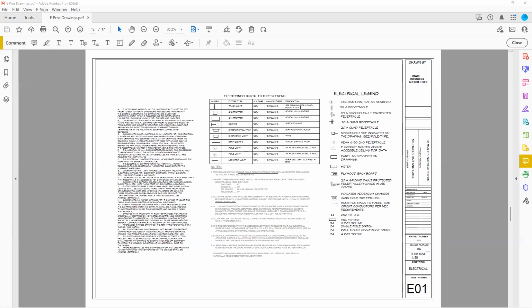So what's important here is sometimes there's also a fixture type that is not just a description like this, but it's actually like an F something, some number. And you can come and look at the light fixture schedule, see that that symbol is in a certain room, and then look at the box and make sure that the box of the fixture you're about to install has that type on the box as well, so you know that you're putting up the right light.